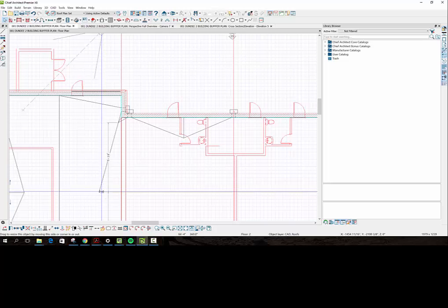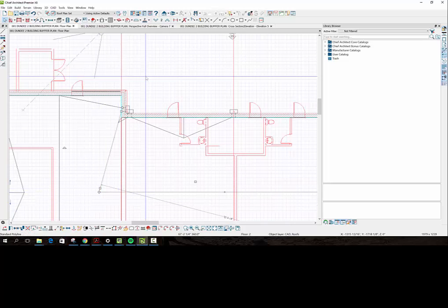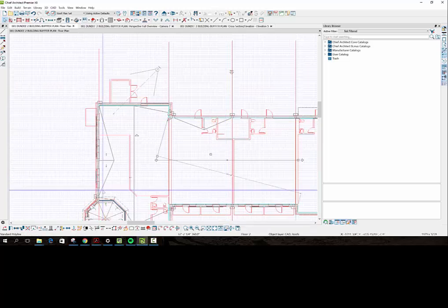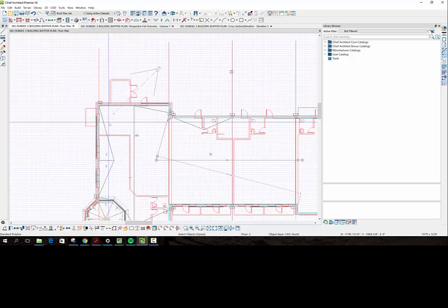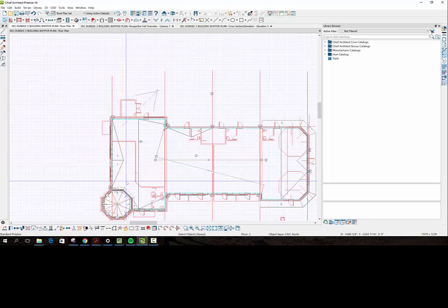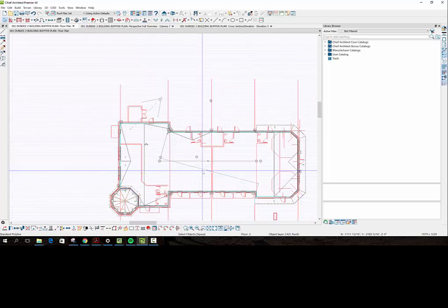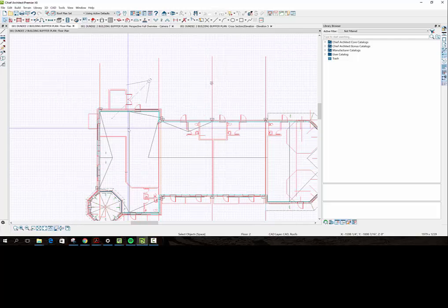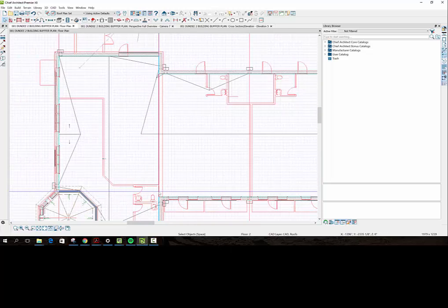And it's going to be just field built with some tapered insulation. All these crickets will be built with tapered insulation. I'm going to taper the insulation. Yeah, it's a long ways to taper. It'll be a lot of insulation. But at least it's better than all this being just sloped. There's that. Even if we did interior roof drains, we have to figure out how the heck this geometry drains, and you'd have all sorts of monkey business as well. So there.